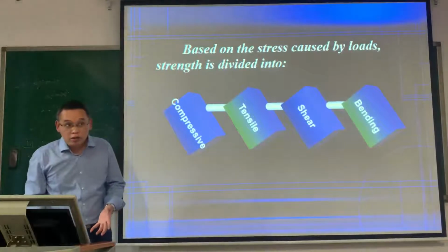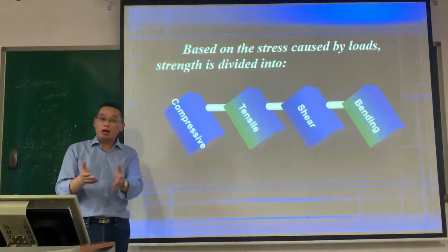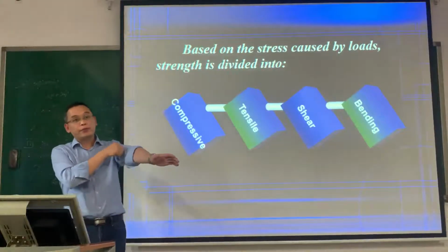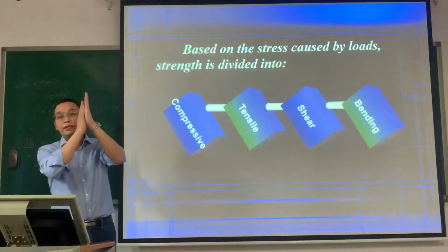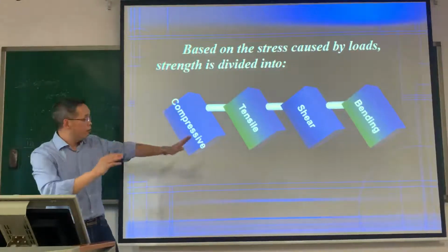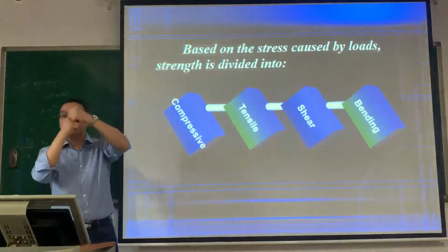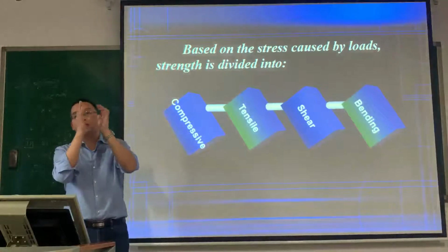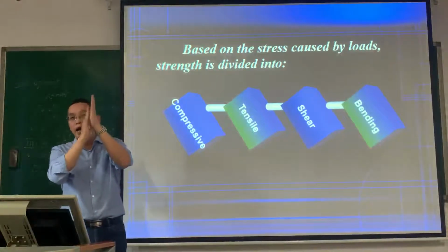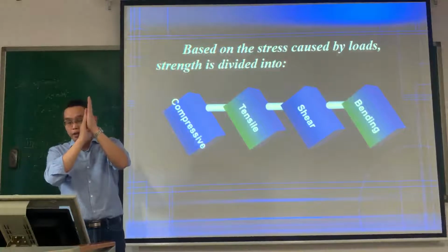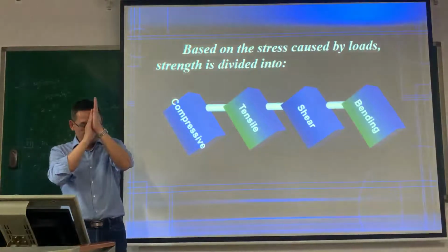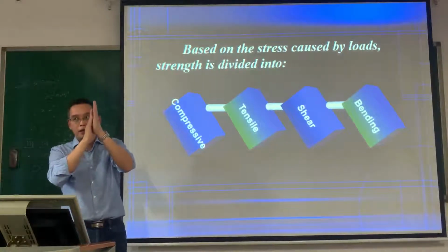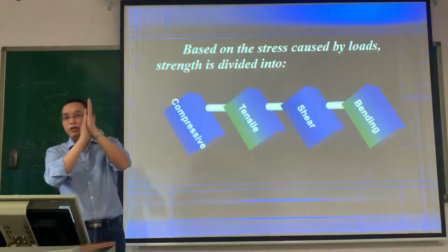How is the load applied for shear? For compressive and tensile strength, there is just one specimen. But for shear, there are two specimens. This is one specimen, and this is another specimen, with a contact area between them.